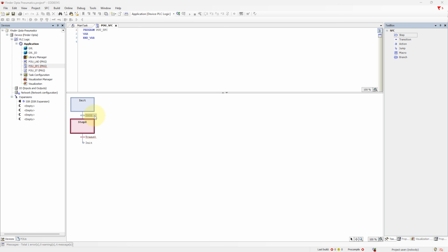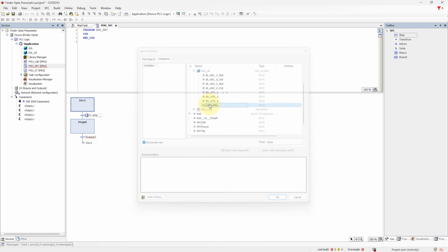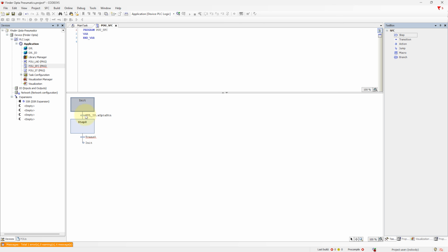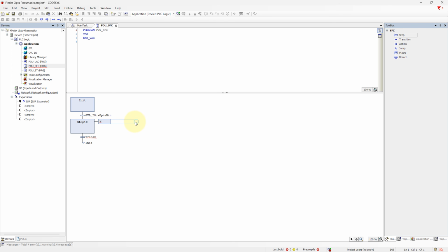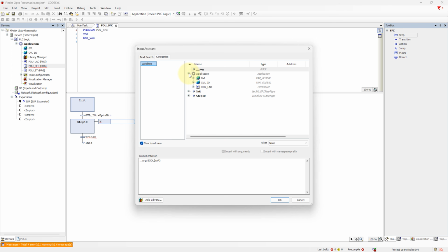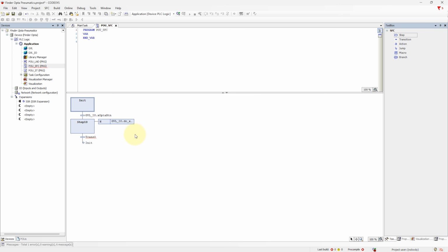See how efficiently you can write such a sequence. Here, we will directly refer to our button, meaning we trigger the sequence with the button. Let's move to step 10, as we described earlier. Here we need to power one of the coils. I click Add Action. I choose the coil that we will power here, and voila. The remaining coils will remain unpowered.